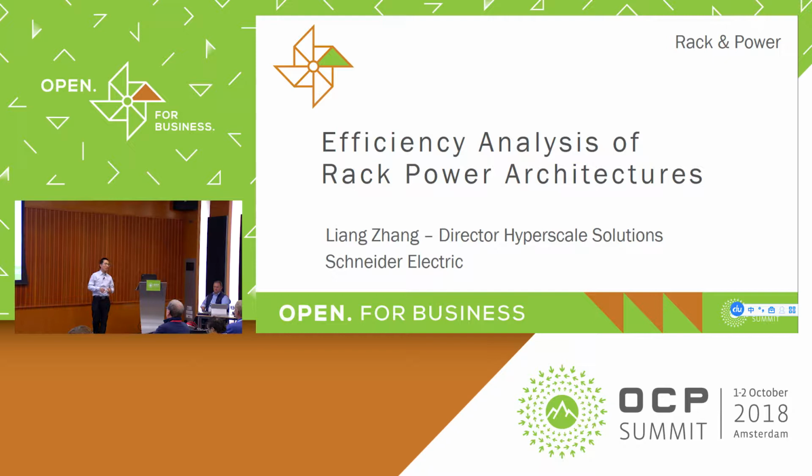Currently, in general, OCP brings a new concept of centralizing all the power shelves, with the output being a 12-volt busbar. Sometimes some companies use 48-volt. We heard there are lots of savings between the traditional server architecture and OCP 12-volt, and lots of savings on 48-volt. So we did some analysis to consolidate all this data to see whether it makes sense or not. I'm going to spend about 10-15 minutes presenting our findings and leave some time for questions.